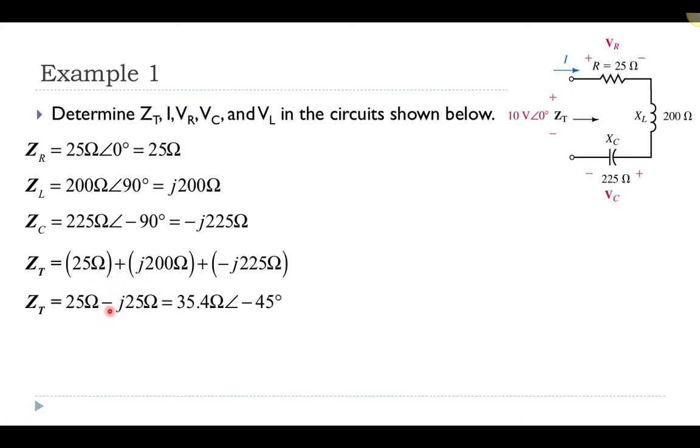So the fact that this is negative means that that capacitive reactance, which is larger than the inductive reactance, is dominating over the circuit. And it looks like, when I look at the total equivalent impedance, that I have a resistor and just a capacitive reactance component, if I just looked at the total equivalent impedance together.